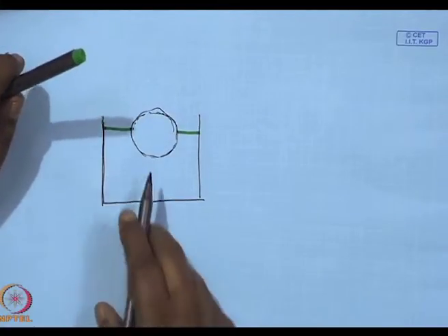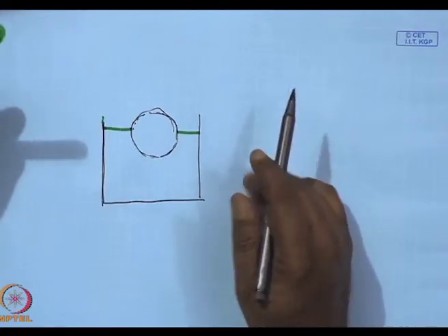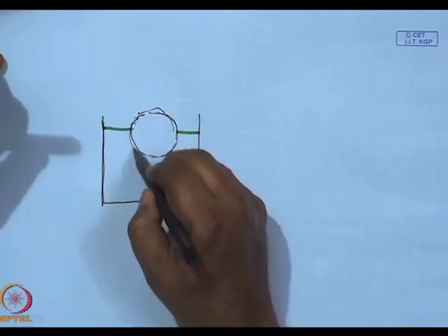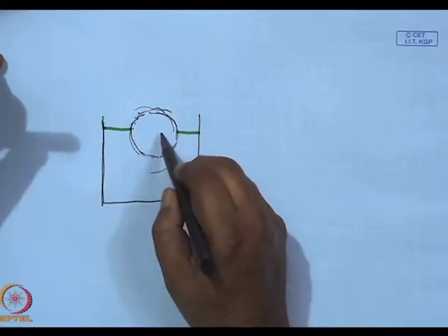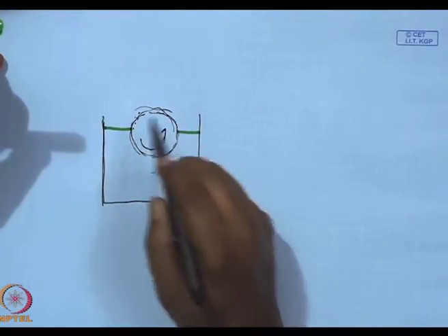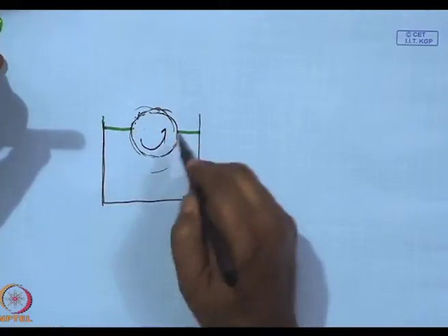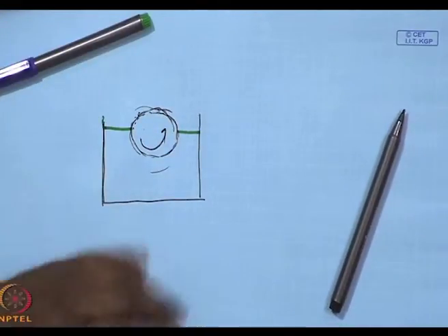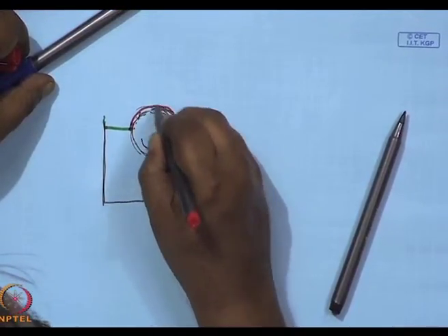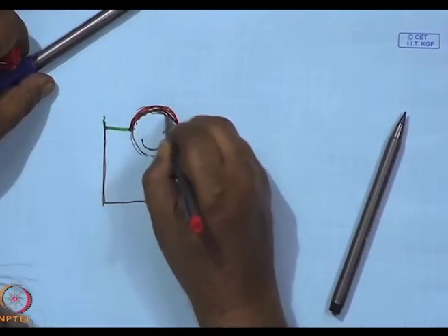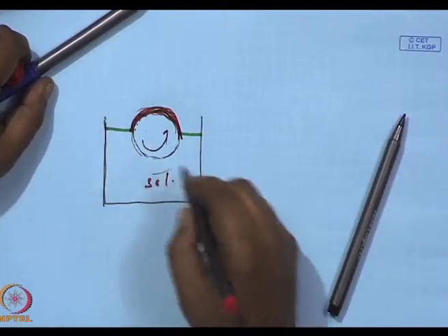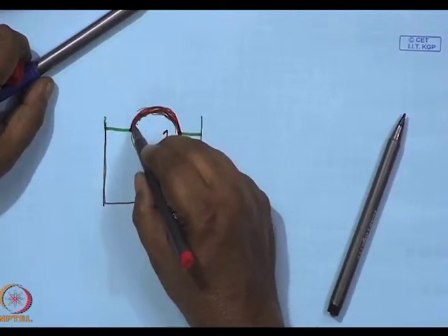we say have a solid shaft, that is this, or for simplicity's sake, let us say we have a cylinder which can rotate in this direction, and the surface of the cylinder is such that when it rotates, it picks up this liquid. This top part gets coated with this sol as it rotates. So, as this cylinder comes up, this top part is coated with the sol.